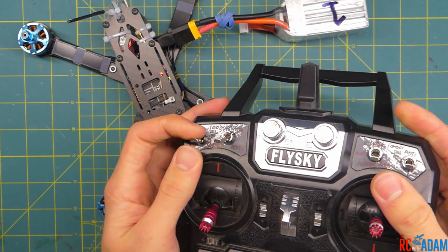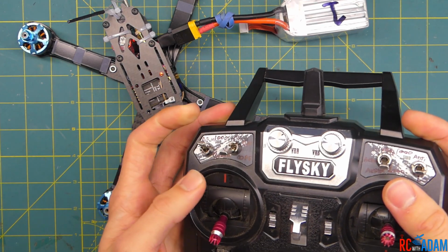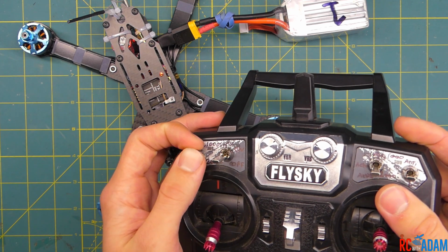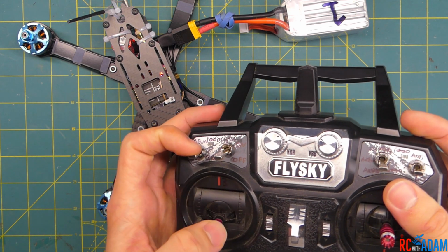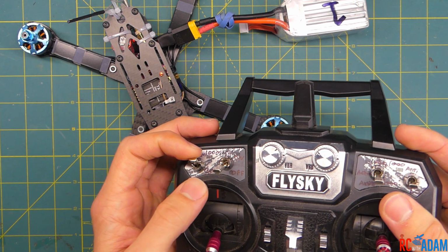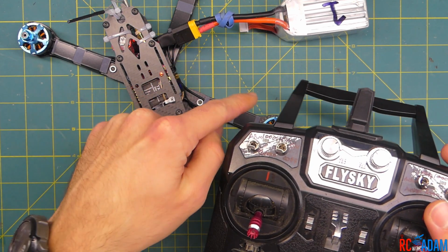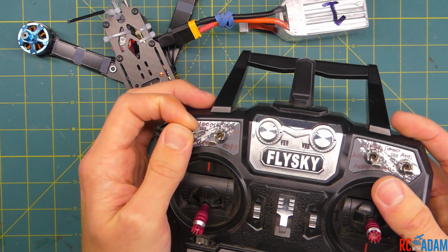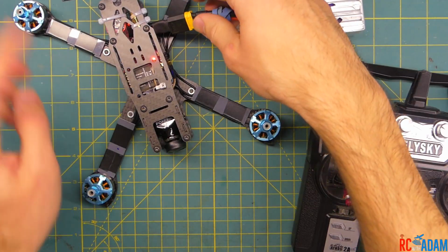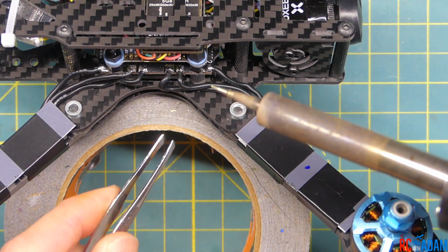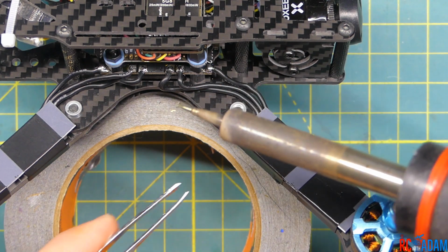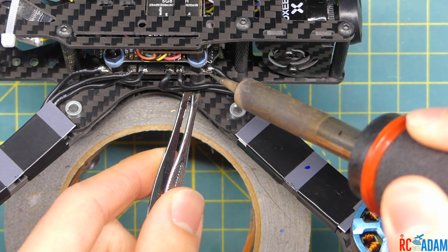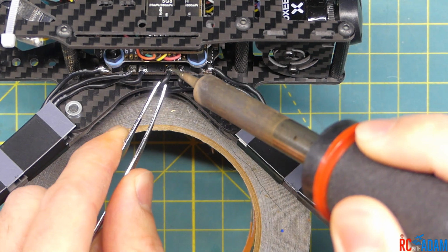Let's see here. Turn everything back off. Unfortunately, if you have a failsafe, you'll probably have to unplug the quadcopter and then plug it back in before you can arm again. I'm pretty sure that's standard. Now let's swap these motor wires. Take two motor wires. It doesn't matter which wires they are. And at this point I realized that it is sort of problematic if you have one of the wires incredibly shorter than the other.